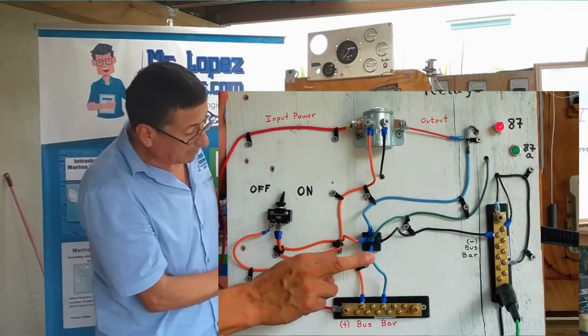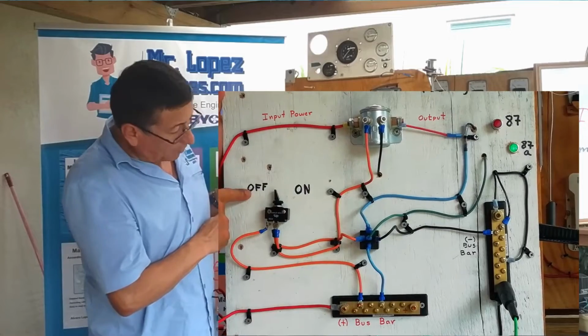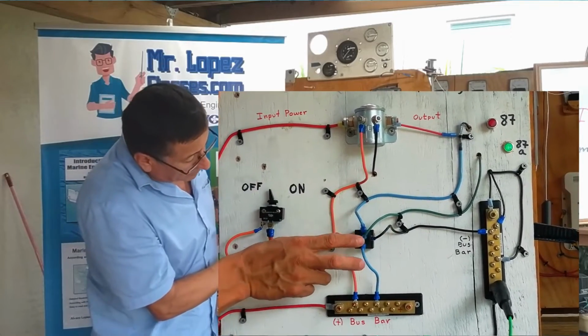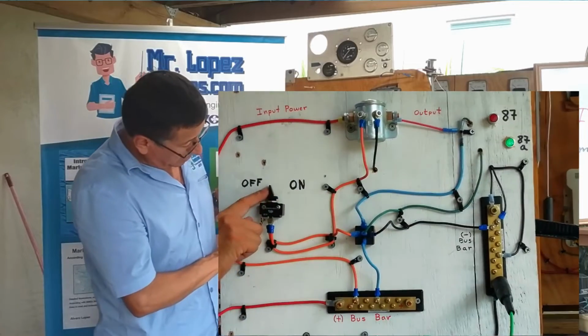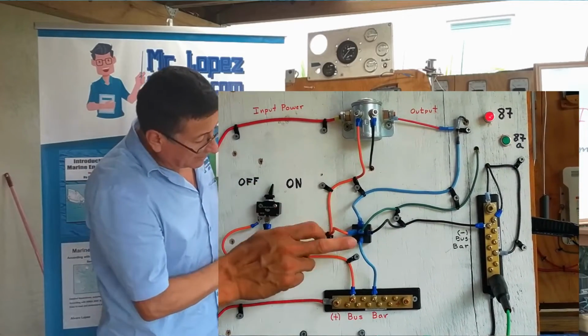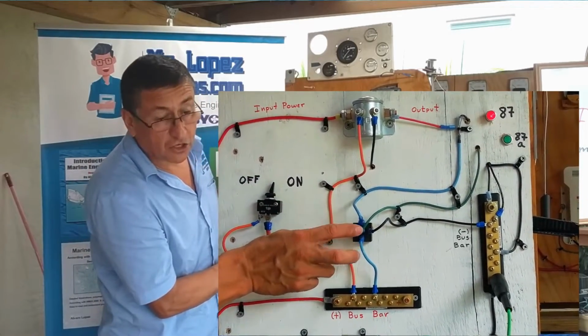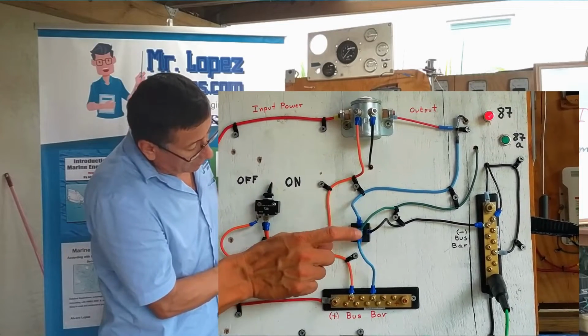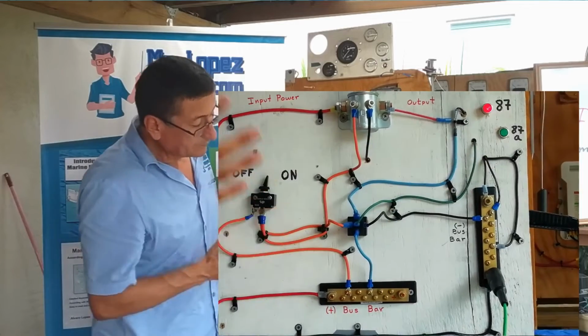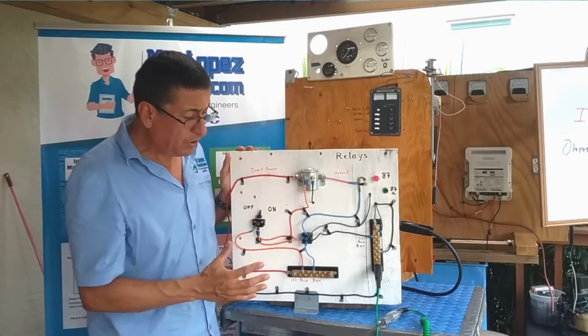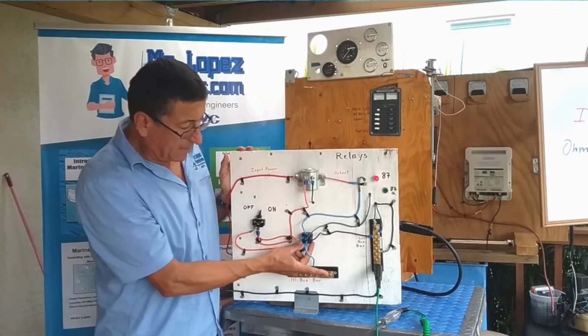Okay, now we are going to check the middle one. No power in the coil. The connection is on. The light is on. Now I power it. The connection is disconnected and there is no power between 30 and 87A. Off. This is the procedure. It's simple to check that relay, the bus relay.